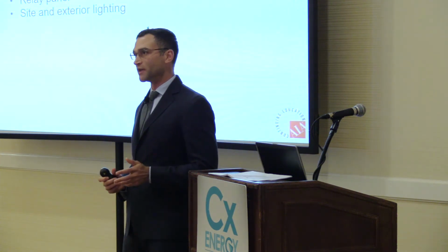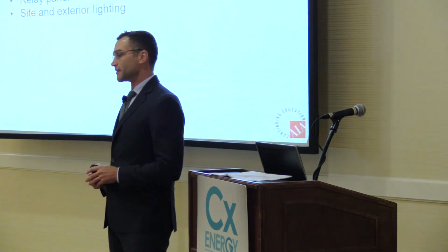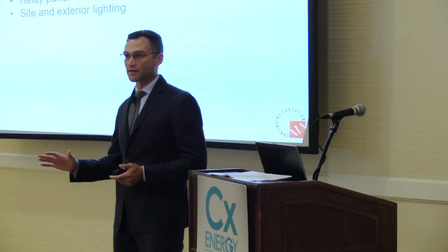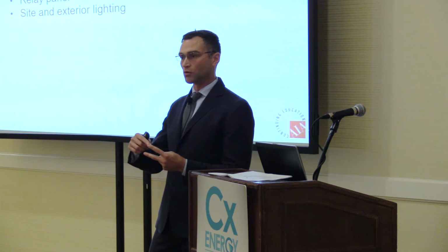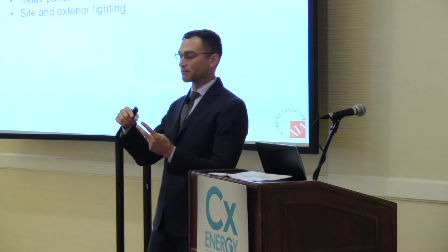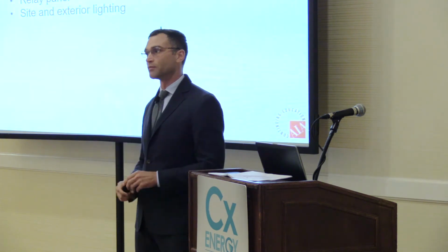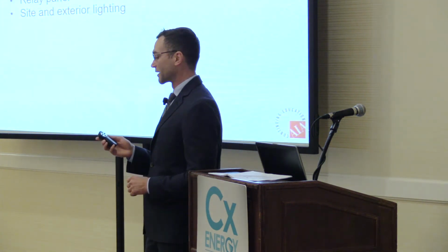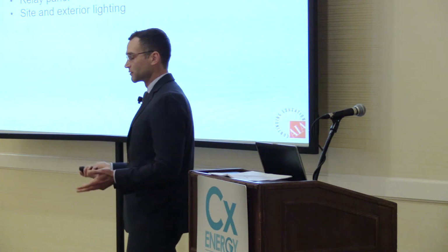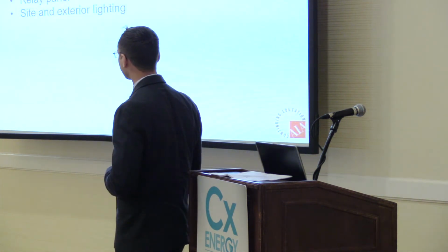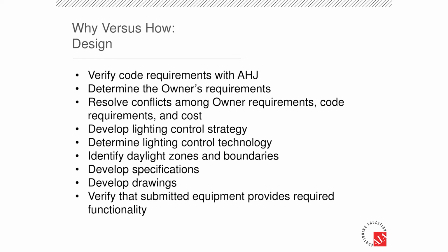The other form would be automated control, sweeping lights on and off as a whole and in area zones. So we really break it up into local, where you physically need to be present, and then, kind of a catch-all, the other type of overall themed lighting control where you sweep large areas off and on. These are the kinds of things we do during the design process to decide what we do about lighting controls and what we have to do.